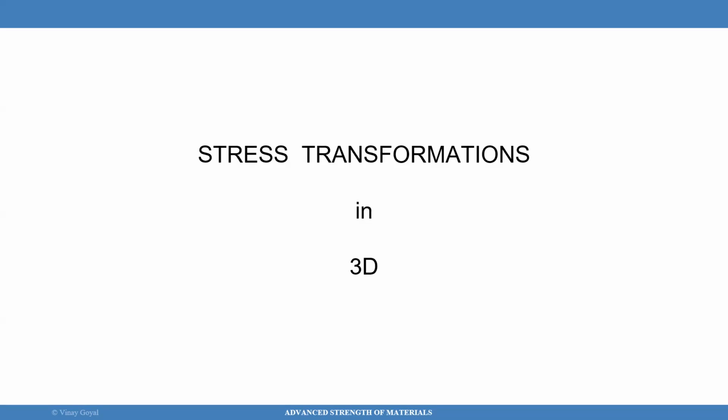And we learned about the idea of principal stresses, an oblique plane whose orientation is such that the tractions are normal to that surface, but there are no shear stresses, or tangential stresses, in that plane. That concept is quite interesting and useful and can be used to predict the failure of brittle material. We've also covered the idea of stress transformations afterward.